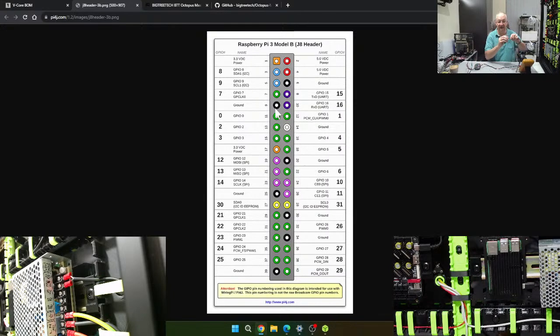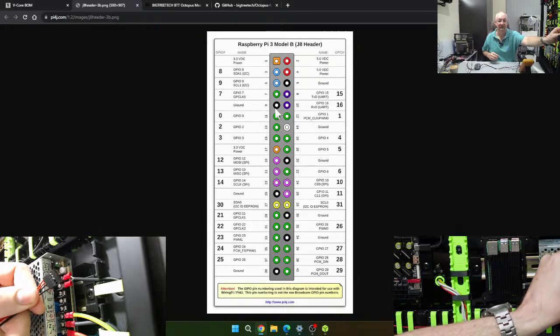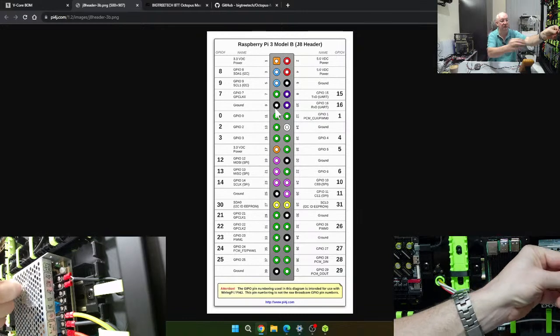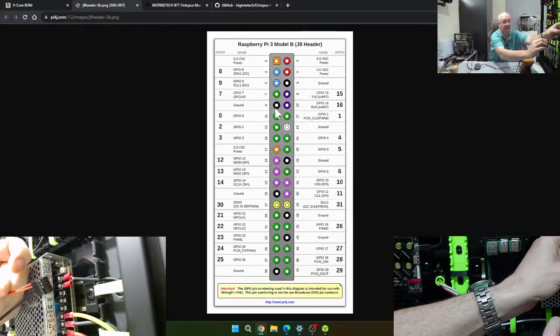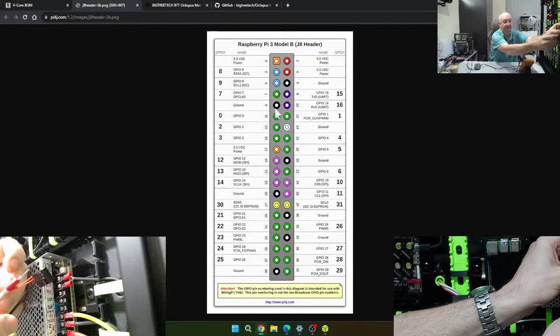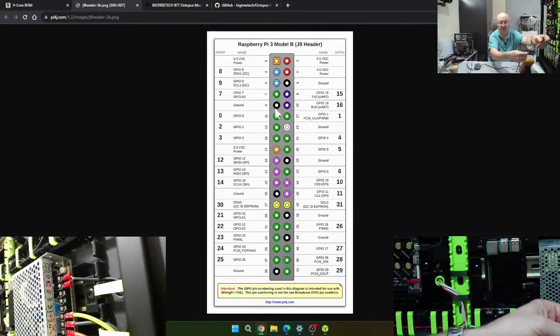Now this connector that I have, which I'm not going to be able to get into focus too easily, I'll just hold it like that for a second, you can see, is already pre-configured in that way, and it's got 2 wires. A red wire that's basically joined together goes to the red, because this was built to actually power a Raspberry Pi from an external power source.